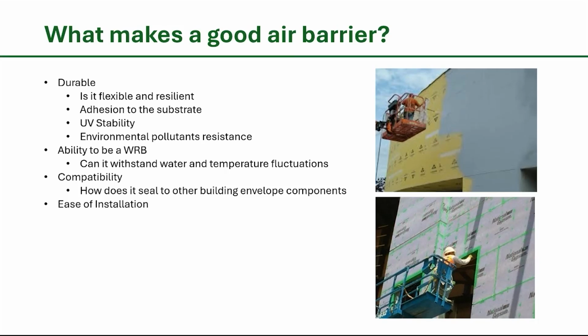The other thing is compatibility. That's the other thing that you're going to think about when you're selecting an air barrier. How compatible is it with the other sealants that we're using on the building? How easy is it to install? Does it need special detailing, or can we stick the waterproofing membrane right onto it, or stick it right onto the waterproofing membrane coming up from the foundation? Can we run the roofing membrane directly onto the air barrier? Does that need special detailing? All of these things can drive different chemistries and different formulations of air barriers.